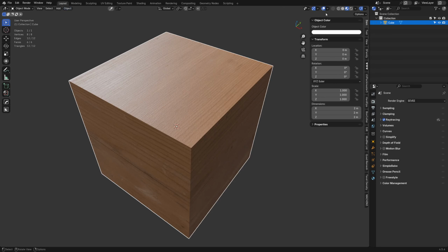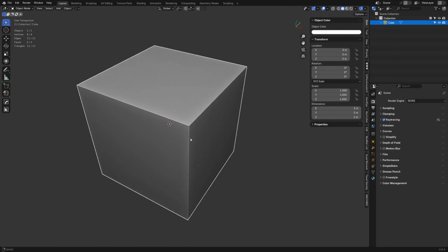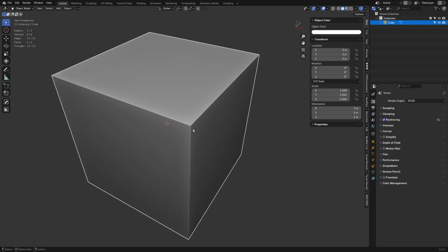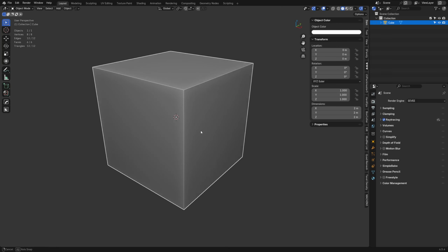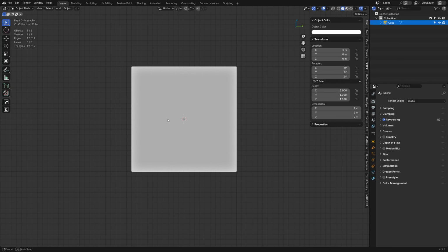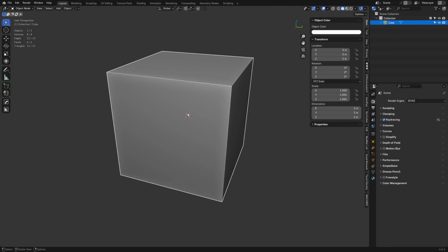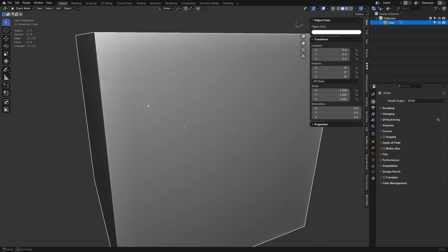Now we're going to go back to layout and I'm going to switch with Z to go to solid view. As I'm working here, there's a couple of navigation things that'll help you out if you're new to Blender. First, control middle mouse click is zoom in and out. You can use the mouse wheel too, of course, but shift and middle mouse is panning. Orbiting is just middle mouse. But if I'm orbiting, I'll hold down Alt and it'll jump me into side views like this. Or you can hold Alt and middle mouse click and gesture, and it will jump into right, left, top, every other view you want. Tilde key, view left, view right, view selected, you can orbit out of those.